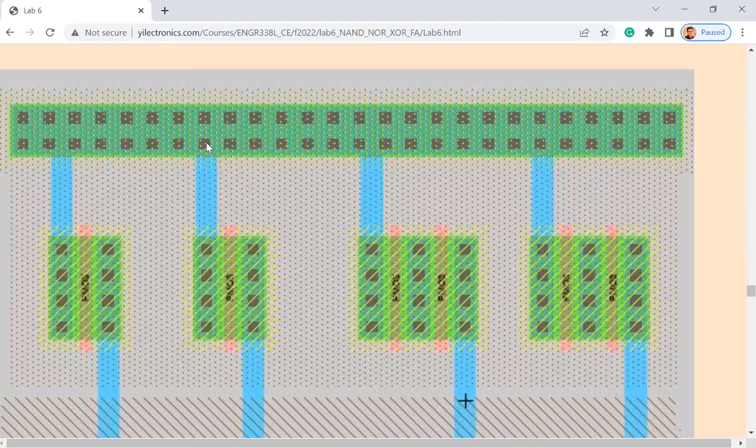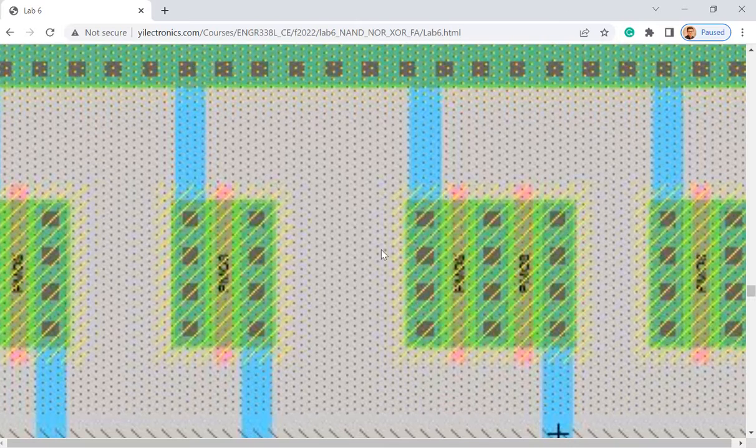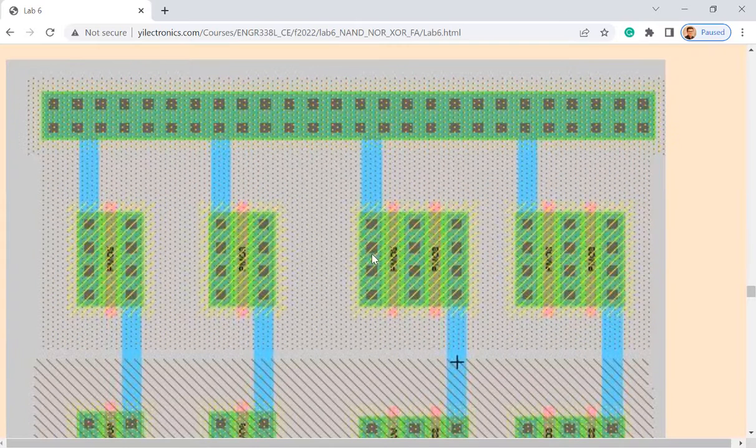Okay, so which means in electrical VLSI by default, the dots are N plus, defines the area of N plus. Okay, and you are wondering, why do we have N plus here? For the PMOS transistors, there are so many N plus diffusion as well. Does that make sense?